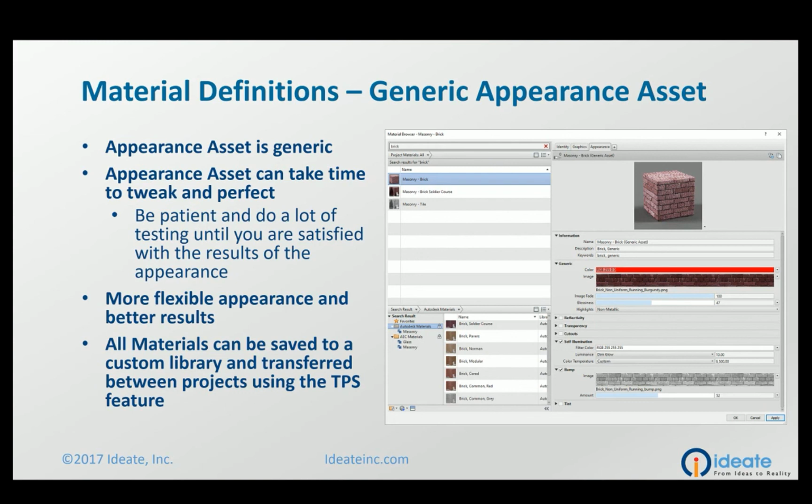And remember, if you download images from the internet, never put them on your desktop. Because Revit doesn't bake those images into your Revit model. So when you hand that file off to somebody else and they go to render it to the cloud or render it on their machine, it won't find those materials. So managing those, you have to be very careful with that too. Put it in your project folder and reference it because it will create a path to that. Make sense?